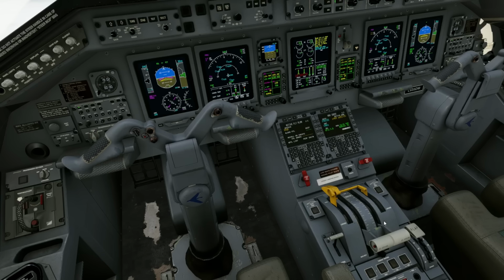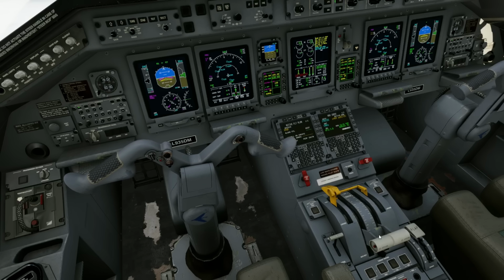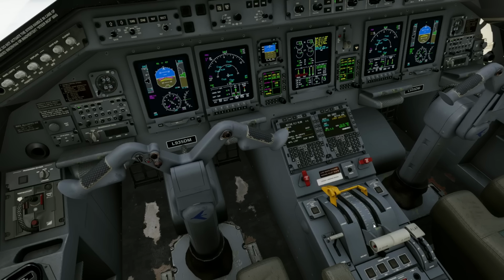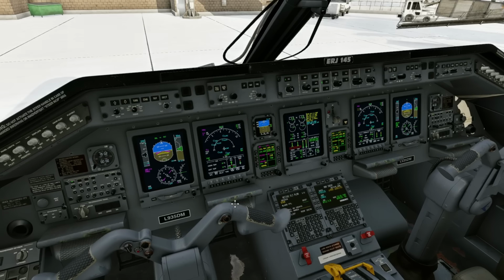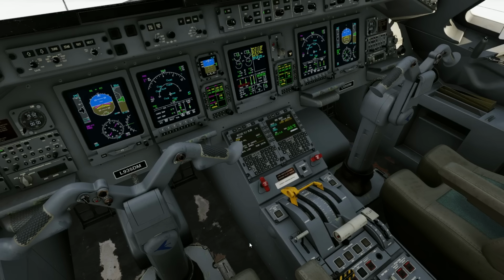Now what you want to do is complete a control check, verify that it is actually released. You do not want to take off with the Gust Lock on. I imagine that's quite bad. And now your Gust Lock is free and your throttles are able to move to the full range. I'll set power with the Gust Lock on in a sec, and you can see what happens when you try to push above.